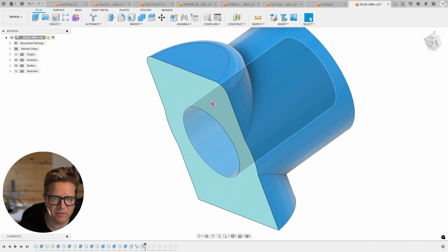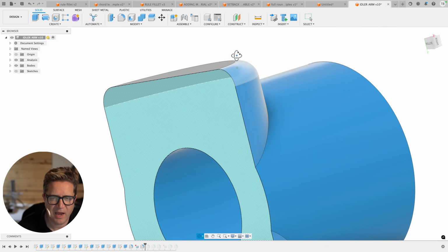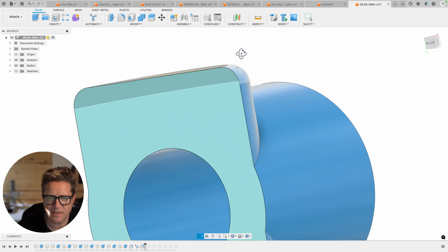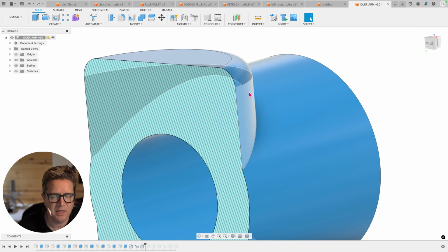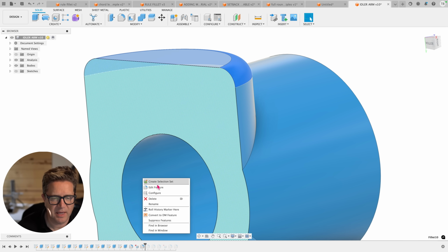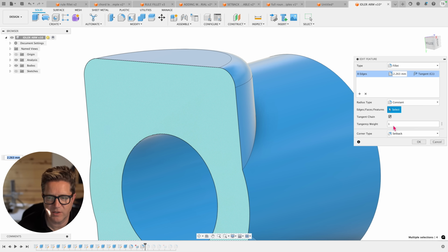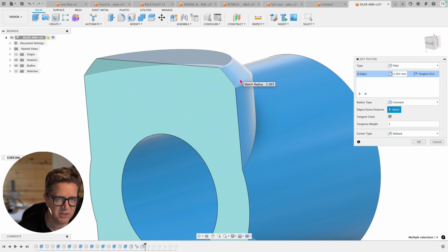So when I've created a fillet, I want to control how it's solving. You'll notice it has this kind of nice smooth tangency solving in between these two faces. If I go back to my fillet and play with this setting called Tangency Weight, and we go all the way down to 0.1, it loses most of its tangency and it's almost like a chamfer.